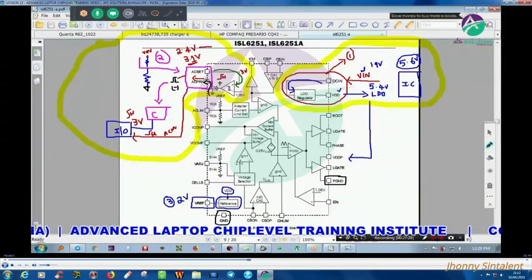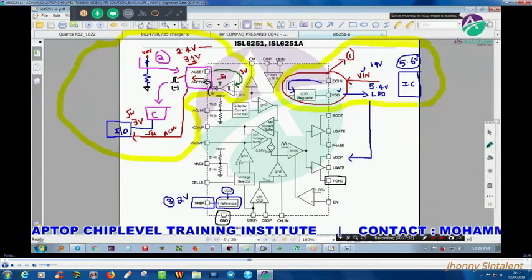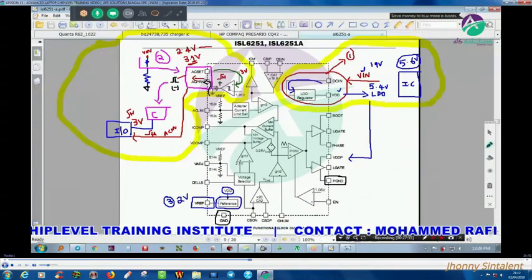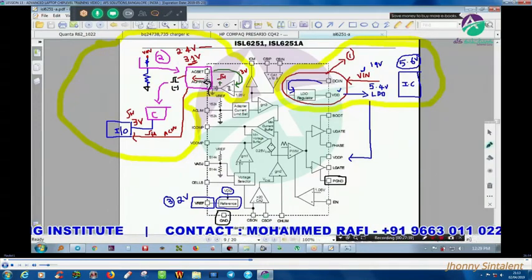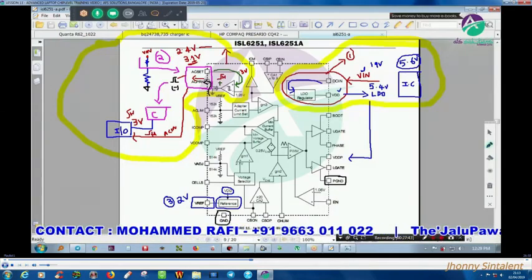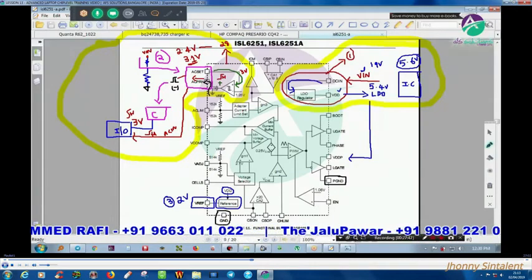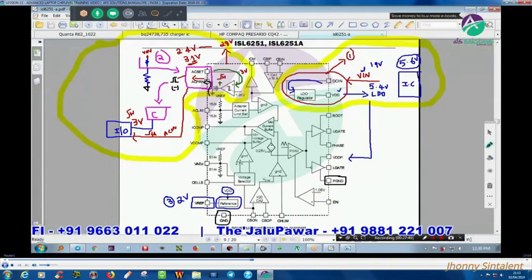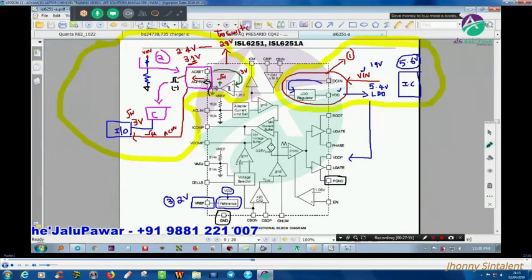In some circuits, when DC in, that is the first part, and the second part confirmation is given to the IO controller, this will release, in some circuits, not every circuit, 28 volts to switch the first MOSFET.